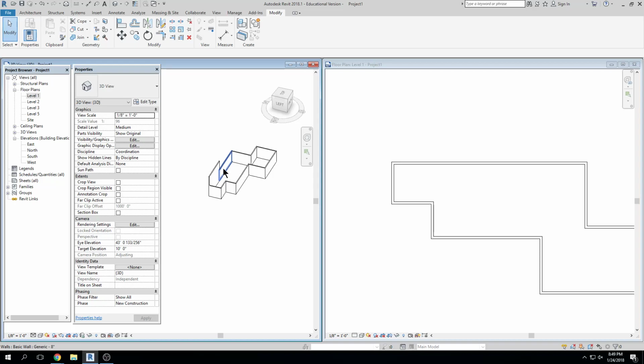Yes, yes. He likes to figure it out. We've already talked about this. So yes, that's a very good point. Here we'd have something like this datum would be bottom of structure, and this one would be something like level 1. Then this would be bottom of structure level 2, and this would be level 2. For each floor, we're going to have a level that marks bottom of structure. We have to have a level because we have to define the walls to go from here to there, not from here to there.